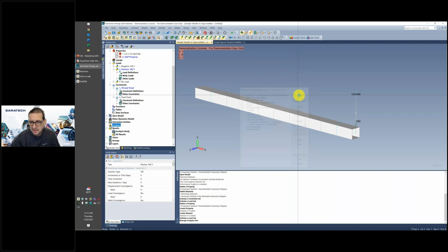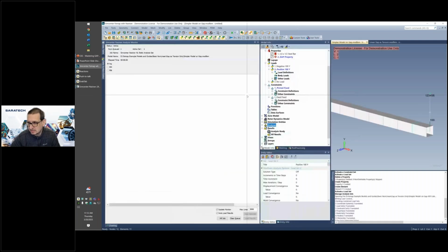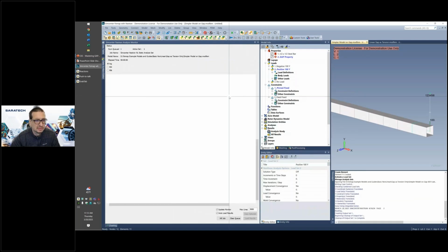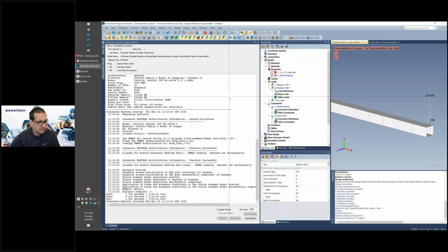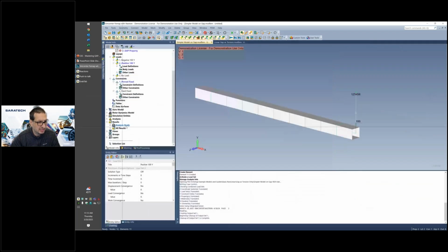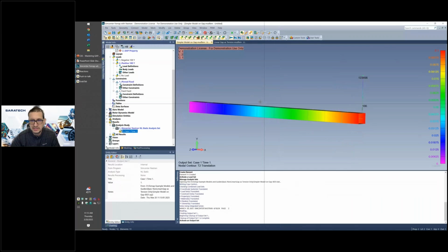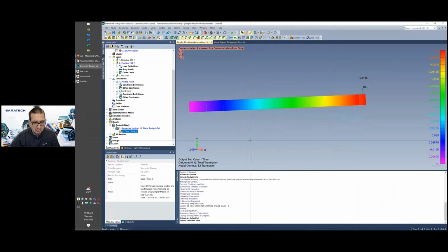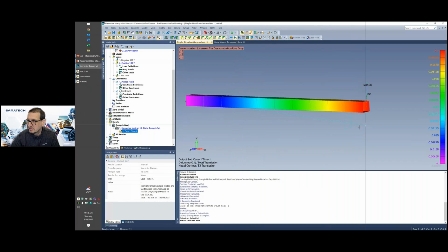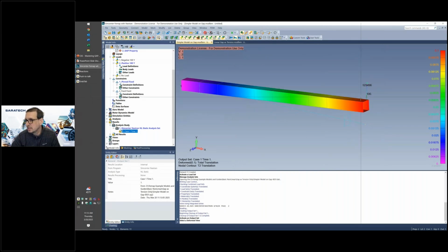All right, with that, we've got a very basic, simple compressive gap element here functioning. Give it a run, should be done here. We can take a quick look at those results, just verify that it did what we expected it to do. And there we go. We are seeing a T2 displacement, or our Y displacement, upwards in the direction of our force, and we are getting a 0.1 displacement, which should be appropriate.